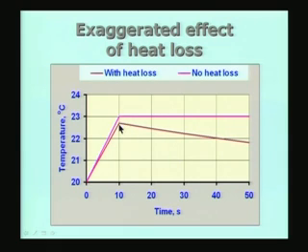And subsequently, let us see what happens. The temperature, instead of remaining constant as in the no heat loss case, is coming down. Of course, I have exaggerated the rapidity with which it is coming down, and if you allow this to come down for a long time, it will eventually come to this value. It will cool down to the jacket temperature.